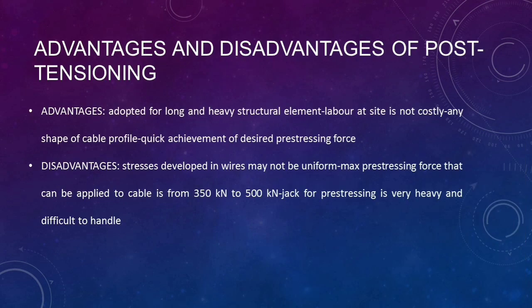Advantages of post-tensioning include the following. Post-tensioning is adopted for long and heavy structural elements. The labor at site is not costly. The ducts may be arranged to any shape to get the required cable profile. And finally, the desired pre-stressing force can be quickly achieved.